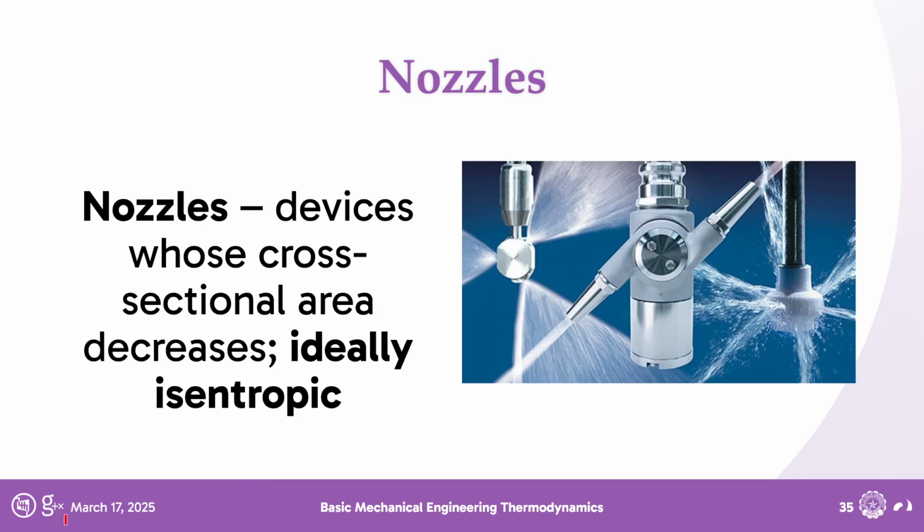And you might be wondering why it's isentropic. More specifically, I think this is supposed to be adiabatic talaga. Adiabatic means that no heat flows into or out of the system. And in this case, the fluid is traveling quite quickly such that the heat has no time to transfer into or out of the system.